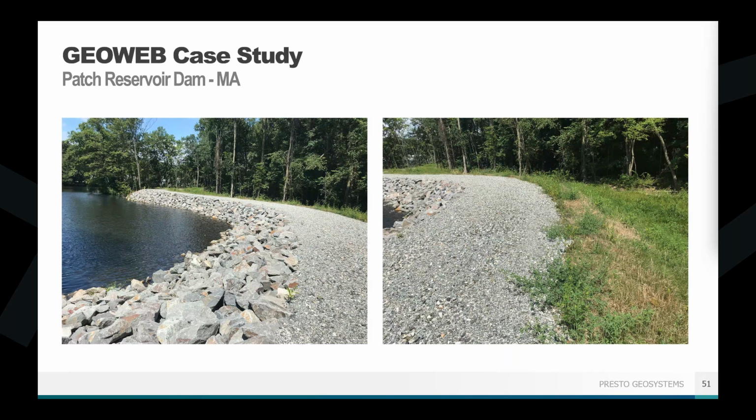So the research that we had done at Colorado State University basically showed the required stone size that was going to be necessary for this specific project. And it was based on the hydraulic flows over the roadway. And again, for this project, not just generically, not being overly conservative, anything like that. So we were able to get the stone as small as possible so that it wasn't some big engineered stone they had to get. And so this way we know that it's going to hold up over time. We know that as that flow happens, this is going to be protected and held in place.